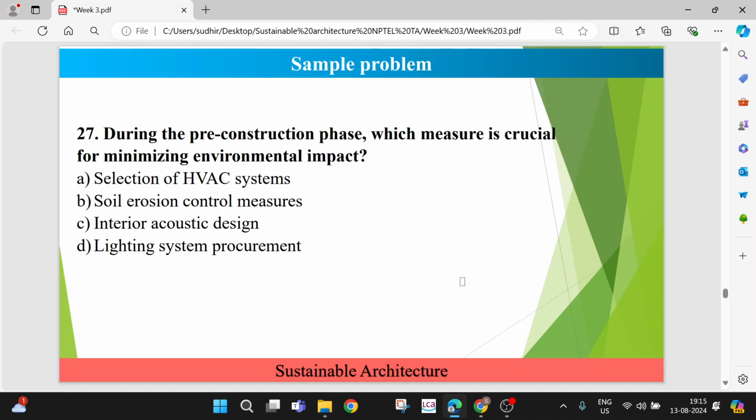When we are designing a building, what is the load estimation or load calculation for that, how much load requirement is there for our building? That has to be calculated and depends on various factors such as the location of your building, the size of your building, the surface area, the surface to volume ratio, the ambient temperature, and the U value of different materials, that is, the heat transfer coefficient values of the materials you are utilizing for construction.